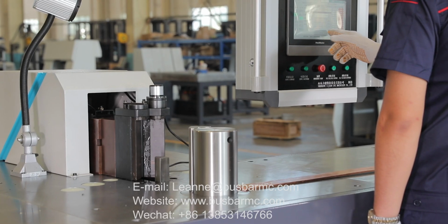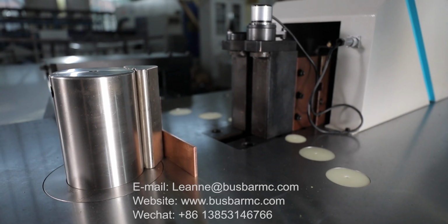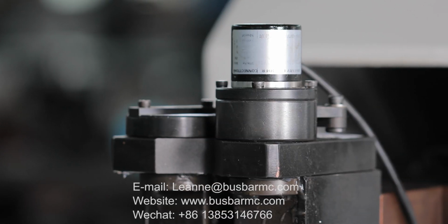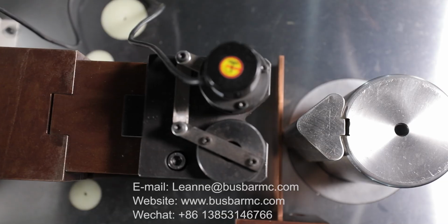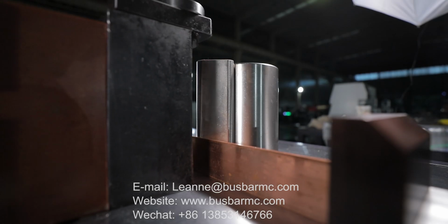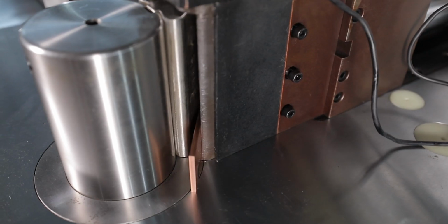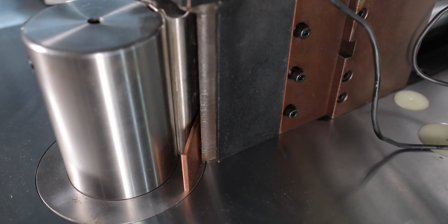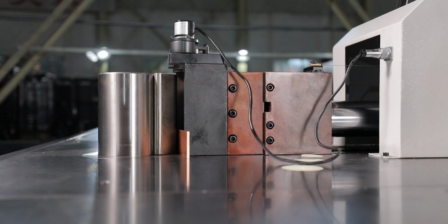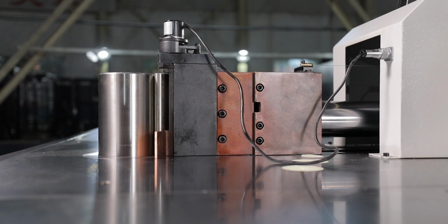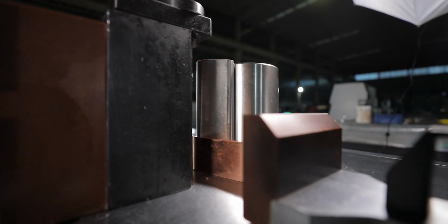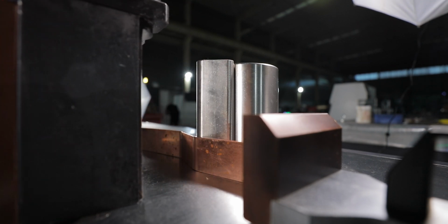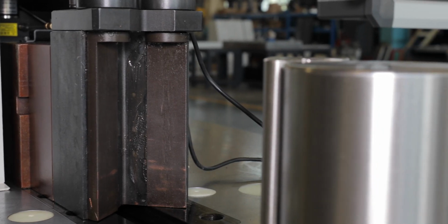The machine can increase the accuracy of bending and reduce the bending marks by adding an electronic die with a rotary encoder. The rotary encoder realizes error-free measurement of the rotation angle. By detecting the same edge of one cycle of the quadrant, the rotation direction can be accurately determined, and then the angular displacement per unit time is measured, thereby accurately positioning the bending angle.